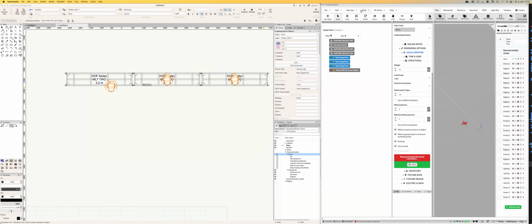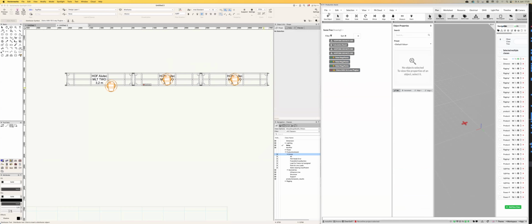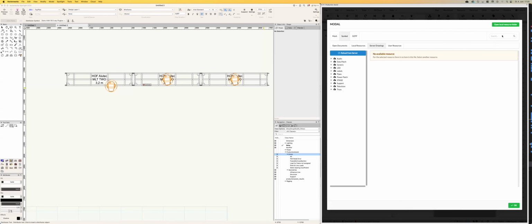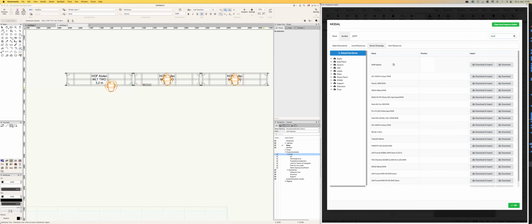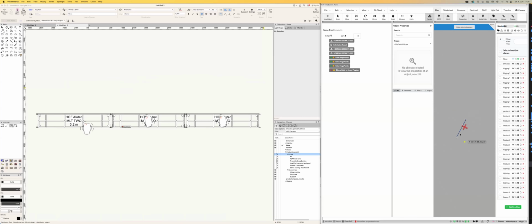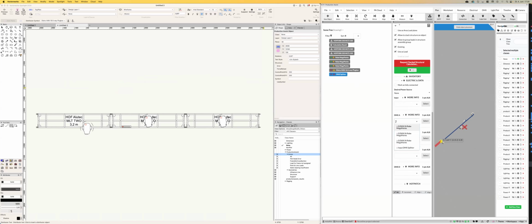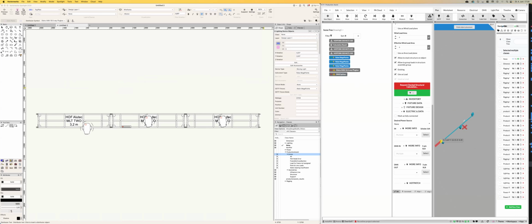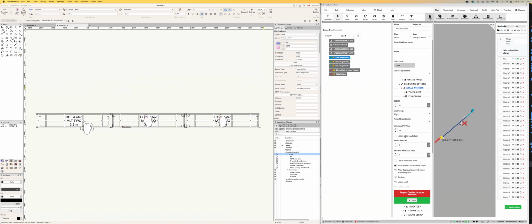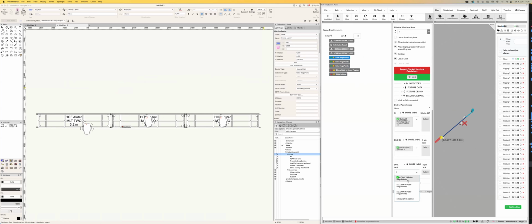What is new now, if you do a cable connection for this, is that you could add a DMX splitter in here as well. So you're adding a DMX splitter to the thing in here. Then you have the DMX splitter, and then you can go into here and say, hey, I want to connect the output 1 to the mega pointy. Then I go to the mega pointy in here with this and say the DMX out should go to the other one.